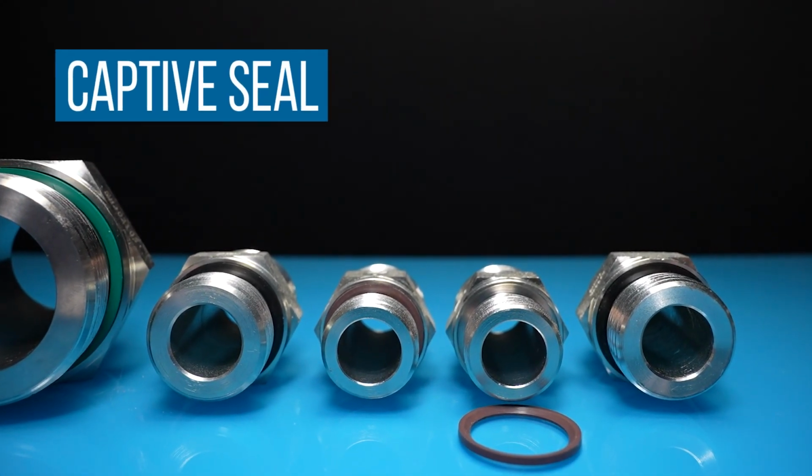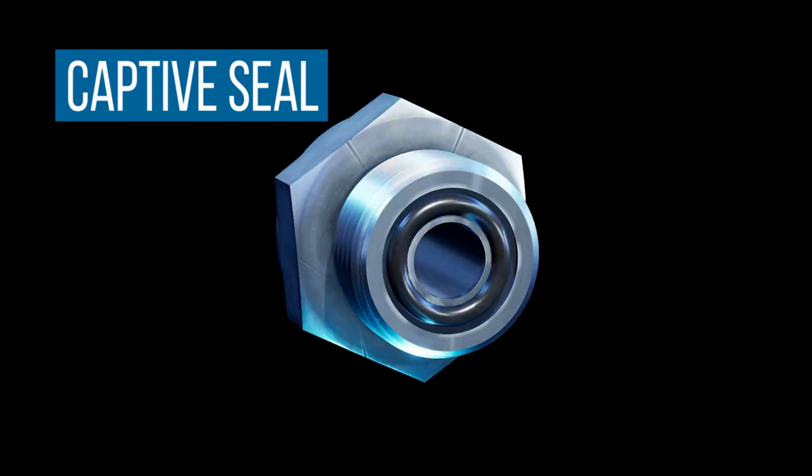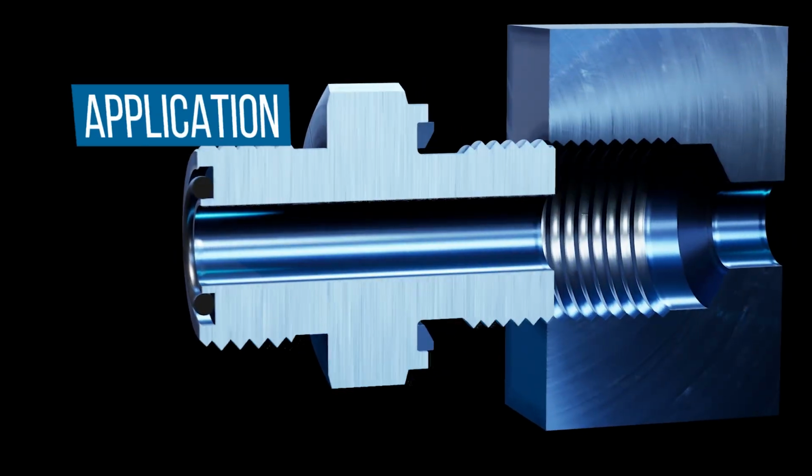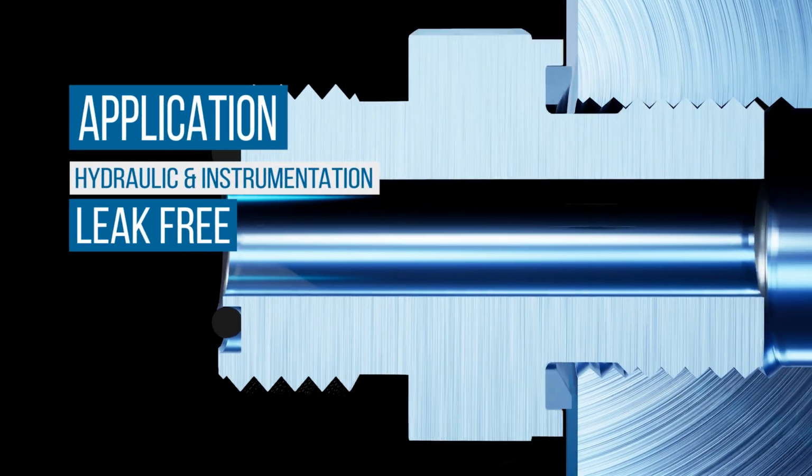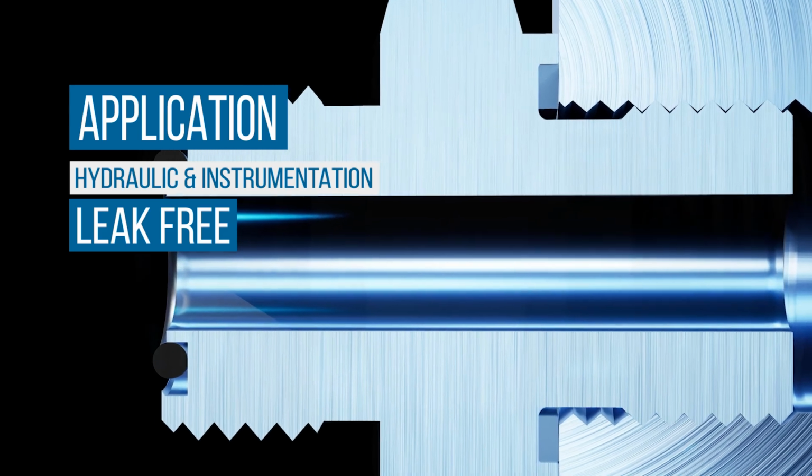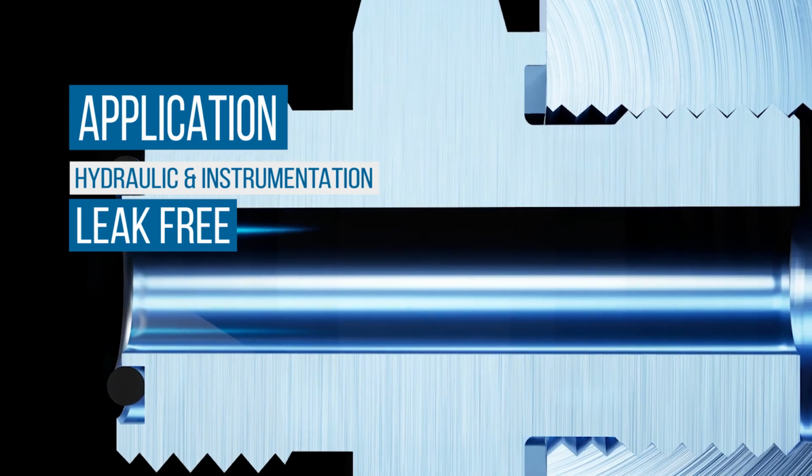A captive seal is another example of elastomeric seal design. Captive seal fittings have a groove machined in the body of the fitting and an elastomer seal recessed and retained by the groove in the fitting. In this design, the seal is achieved as the connection is tightened. The results here are a leak-free and common connection suitable for general hydraulic and instrumentation system applications.